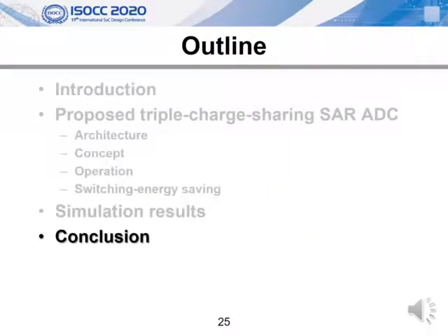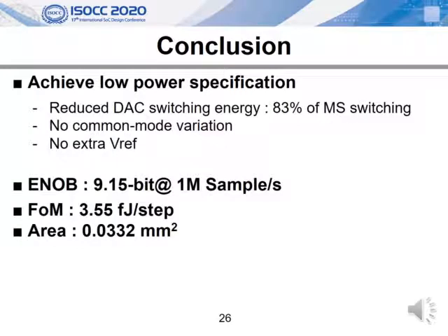I want to conclude my presentation with the summary. In this work, a 1 megasample per sec 10-bit SAR ADC is implemented with a triple charge sharing technique. Thanks to the TCS technique, switching energy is reduced to 83% compared to the merge and split switching without common mode variation and extra voltage reference.